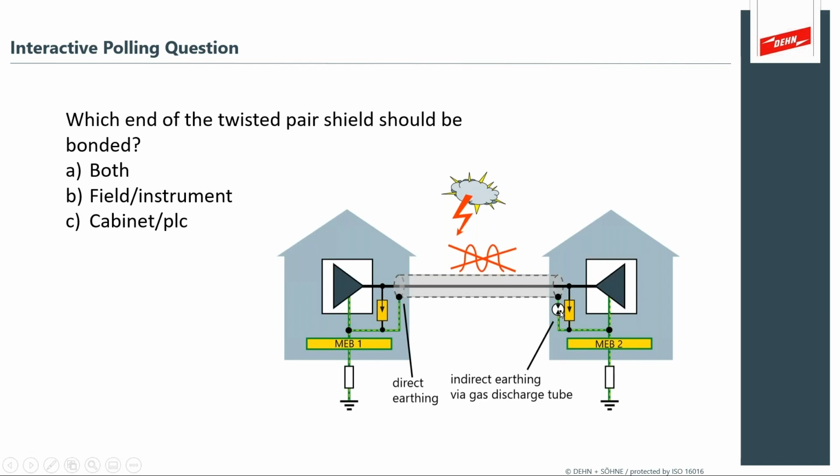So in an application like this, what could work well is to have a surge protection device, particularly a spark gap, a gas discharge tube on that shield to act like a pressure valve. So any other time during the day, it's open and it's not interfering with current. What you don't want is a bond here, because look, these are different grounds.